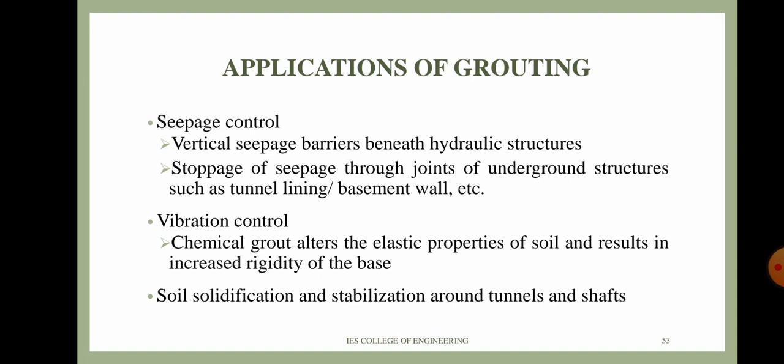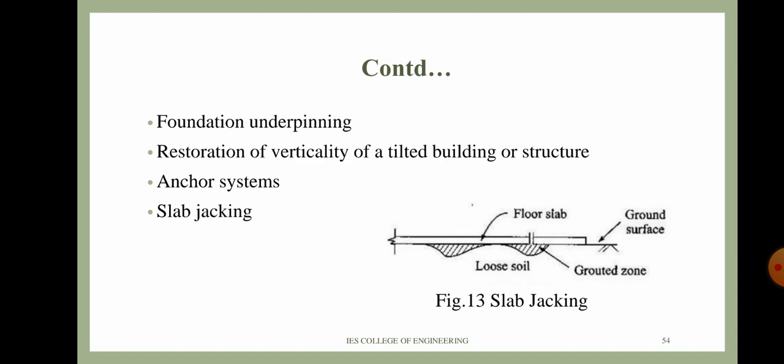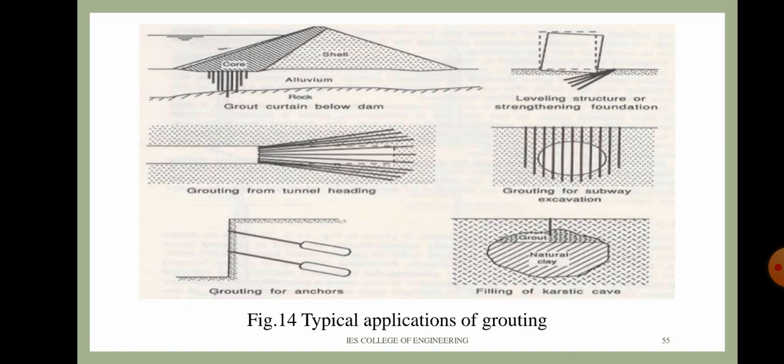And another application is soil solidification and stabilization around tunnels and shafts, and foundation underpinning, restoration of verticality of a tilted building or structure, anchor systems, and slab jacking are the other applications of grouting. Here the figure is shown for the slab jacking, where the grout forms a support for the floor slab, and here different applications of grouting are shown.